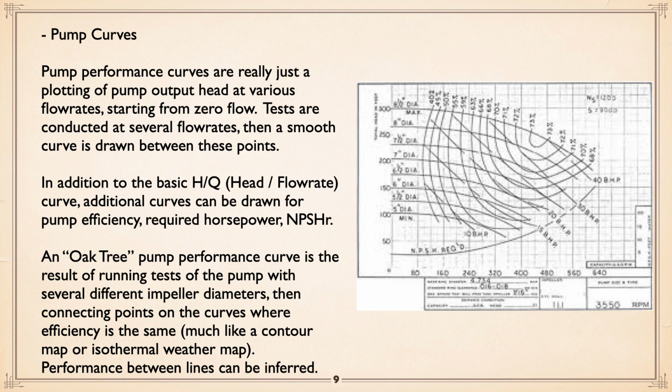The interesting thing is, if you have a 7 3/4 trim on the impeller diameter, it will be right dead between 7.5 and 8. So you can plot that curve and see what it'll do. That allows you, if you want, to have a pump that's trimmed for the operating point you want, or trimmed to take maximum advantage of the horsepower you want, or not go into overload. We'll get into that later. It gives you all that kind of flexibility.